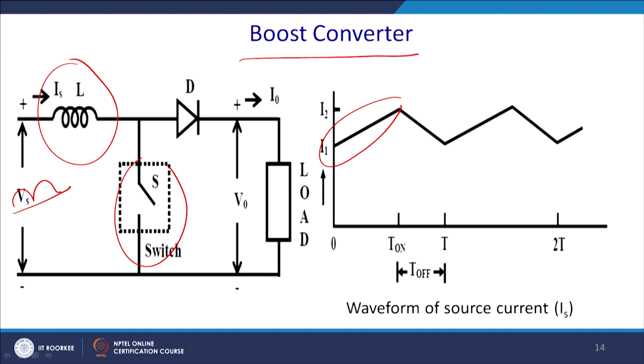and when the switch is off, then there will be stored energy in the inductance, a voltage VL will appear across it, and this voltage and Vs will basically feed the load, and thus you will find that the voltage applied across this load has been enhanced.